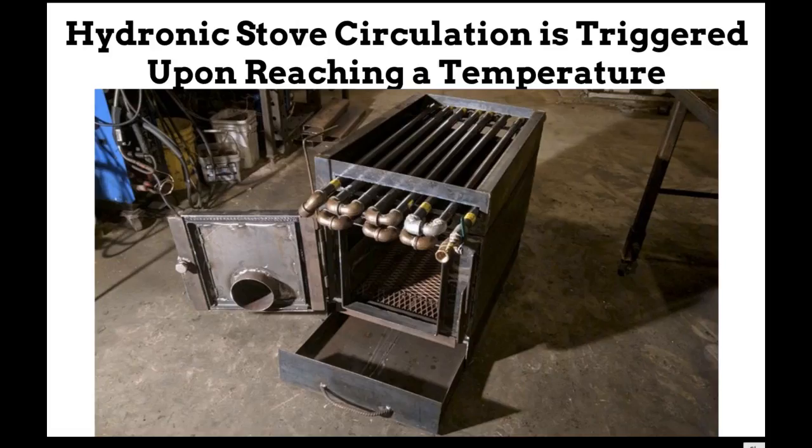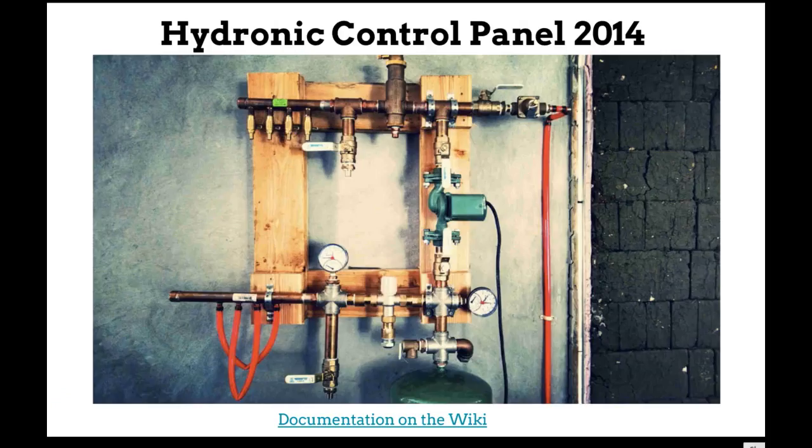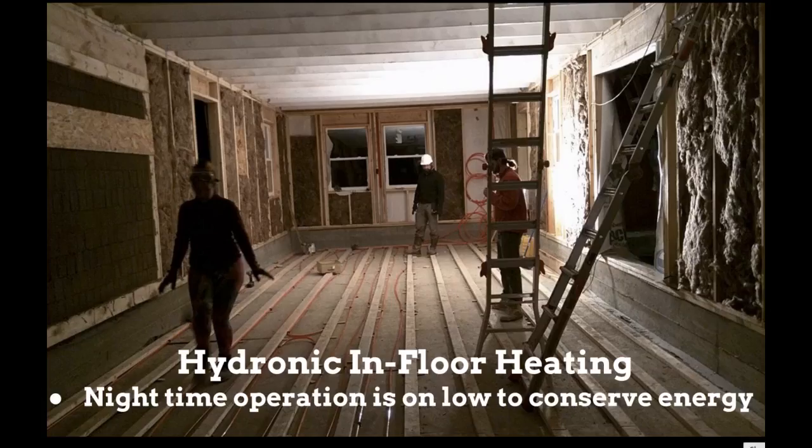Okay, so hydronic stove circulation, that's where the hydronic wood or pellet stove is used. So what happens in a stove with automatic controls, we want to control that. We have a small volume of water that, once the water reaches a certain temperature, you turn the circulation on. The circulation runs through the hydronic control panel and into the in-floor heating. So basically the only thing is that once the temperature of the stove gets to a certain degree, in other words, the flame is on, it goes off when the flame goes out. But basically, you've got temperature activation and also nighttime operation.